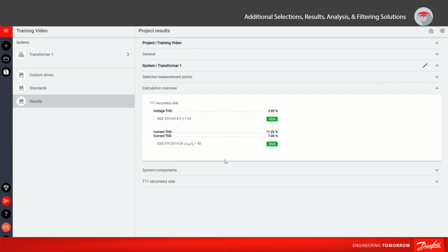This shows that the 35 amp filter can be used instead of the 55 amp filter to stay compliant, while reducing the cost. If the customer is looking to upgrade a motor load in the future by adding a drive load, they wouldn't need to add any additional filtering. In this case, we would recommend selecting the 55 amp filter from the beginning, or go with the 35 amp filter now, then in the future add another drive with an active or passive filter.